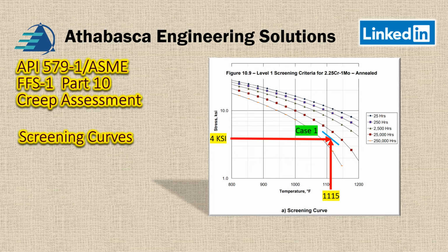Now, here's your temperature, your excursion temperature. What does that tell you? Well, you're off the curve. So that automatically tells you that the level 1 assessment is no longer applicable, because you have to do a more in-depth analysis, because these curves are intended for 1200 and less.